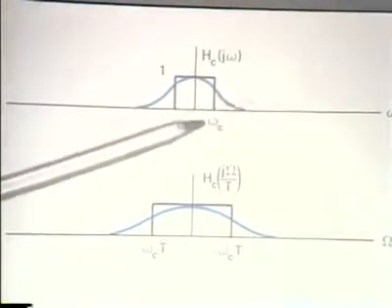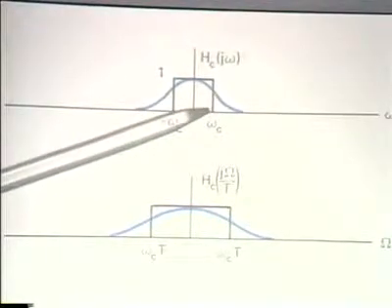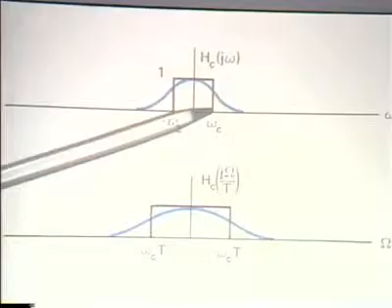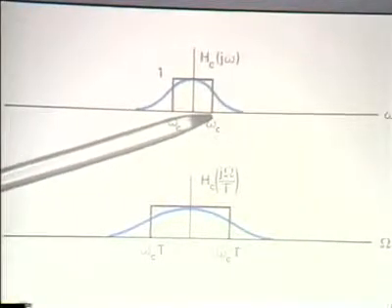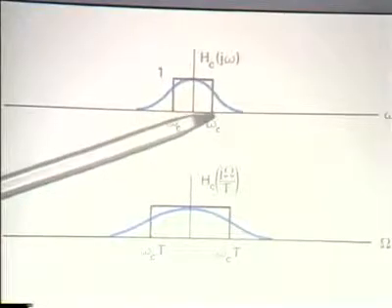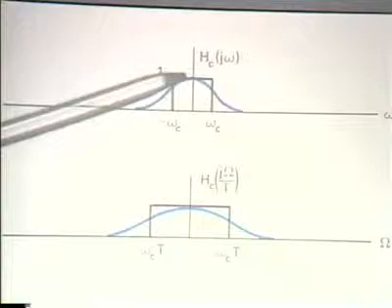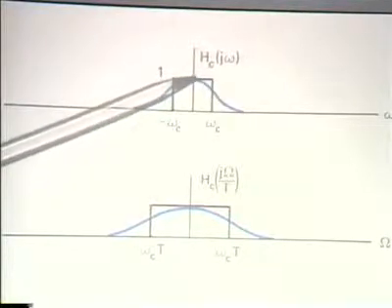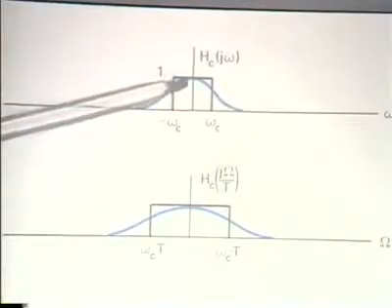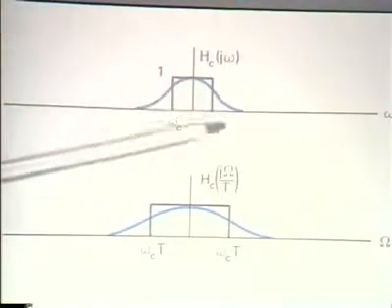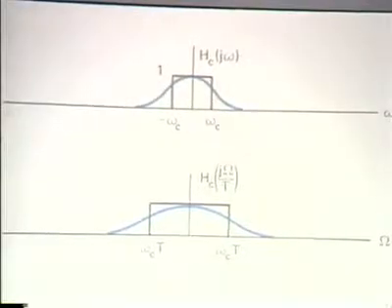And in particular, if I pick the parameter in the impulse invariant design, capital T, as equal to unity, and I indicated just a minute ago that we can pick it arbitrarily, then the procedure would consist of designing the continuous time Butterworth filter meeting or exceeding the appropriate specifications and then going through the impulse invariant procedure.